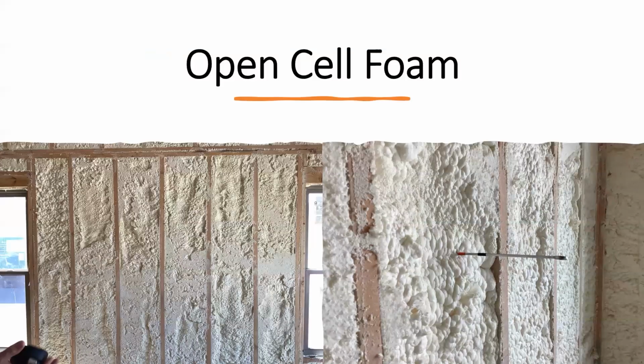Another easy determination is grading of foam. If installed per manufacturer instructions to achieve the proper R value, it's almost impossible to get a grade 1. What usually happens is the installer will install less than the inches needed for the R value required. So the photo on the right is one way to verify the depth and thickness to ensure proper R value.